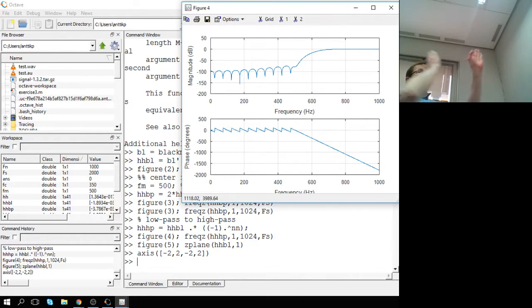Okay, so we have low pass, we have high pass, then we have the band pass filter. Then the only ones missing, well, two of them are missing. How about band stop? Well, you see it here. Band stop is the combination of those, low pass and high pass.